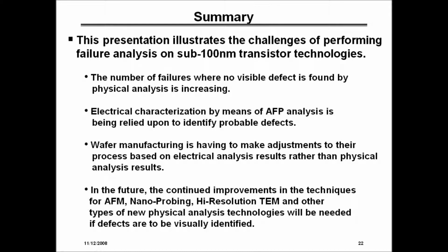with the newer models of the TEM, we recently upgraded to the recent JEOL model. And our TEM expert has been developing a holography technique, which allows the TEM to look at source drain implant. And with that capability, you can relatively easily see the source drain implants.